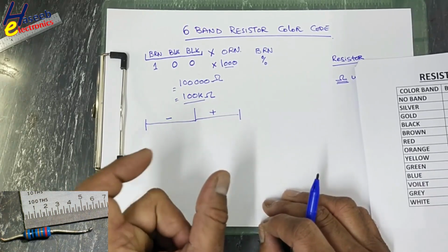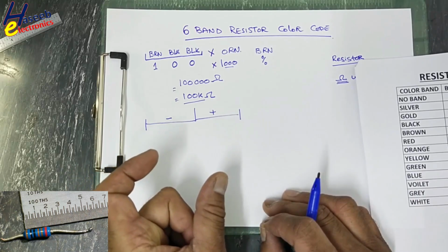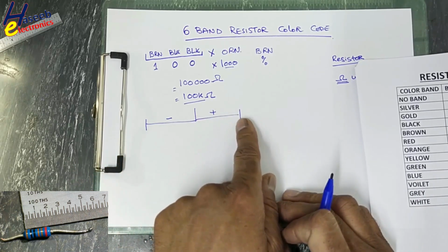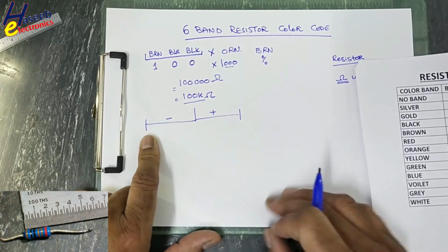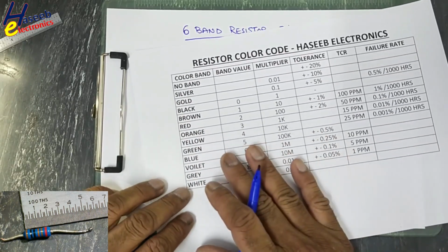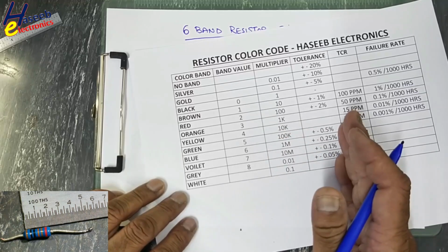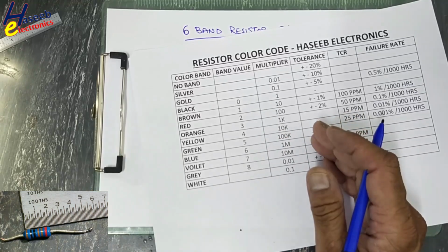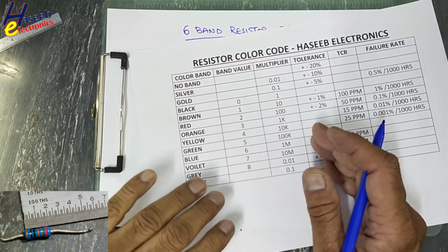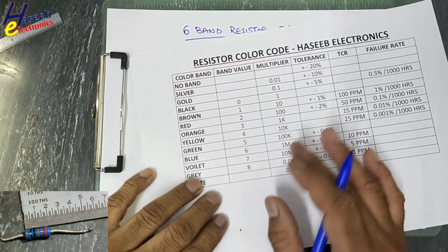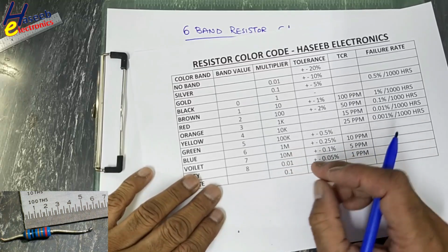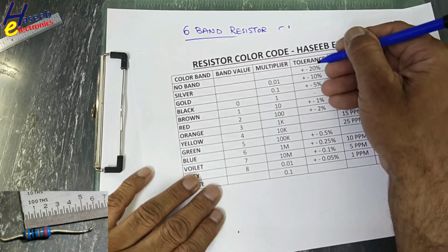That is due to the manufacturing process. This 100K resistor will be acceptable from this range to this range. Some are 5% tolerance, 10% tolerance, 20% tolerance, and now more accurate resistors, called select resistors or precise resistors, provide more accuracy to the center value.